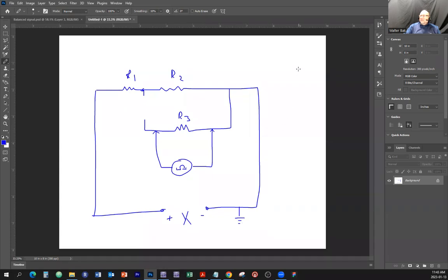And if you have another part of the circuitry, whatever it is, and if you have an active meter, which basically you plug into the wall, it could be connected through to the ground through some other circuitry internally, then it can cause some problems. So then you might have to remove the whole thing out of the circuit in order to properly measure that, all right? But that's what I meant by lifting one leg. Sometimes if you just have one free floating battery operated equipment, it's enough to just lift one leg. You don't have to remove the whole part, the whole resistor.